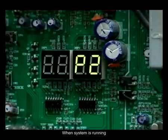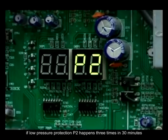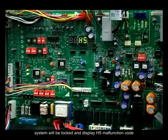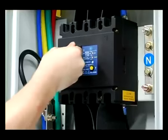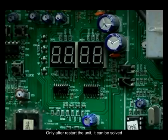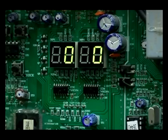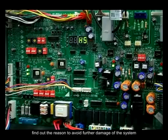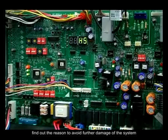When the system is running, if low pressure protection P2 happens 3 times in 30 minutes, system will be locked and display H5 malfunction code. Only after restart the unit it can be solved. At this moment, you should check and repair the system. Find out the reason to avoid further damage of the system.